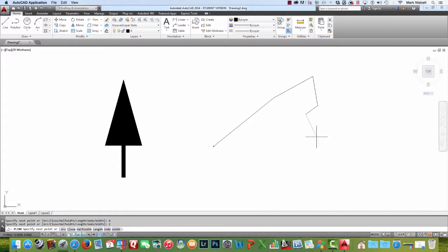But now that we have dynamic input, we really don't have to worry about that so much. Because if I'm drawing a line like this, I don't have dynamic input on, but I can put that on. So I could just basically type in, I'm going in this direction, I want it to be 6, and it goes up there 6. So like that. I want to go down here at 60 degrees, 65 degrees, 4 inches. I can do that sort of thing.